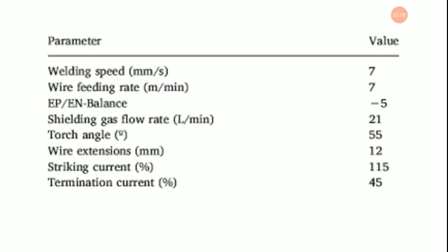As the base current increases, the value of face width is higher. This is because IB is mainly helpful in maintaining constant continuous arc during welding. So it melts more base metal and filler material in narrow direction, so face width increases. On the other hand, as frequency increases, face width goes on decreasing. This is because of more pulse rate and more heat concentrated in narrow direction.